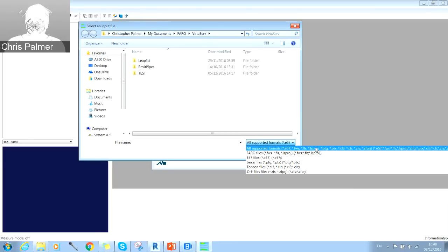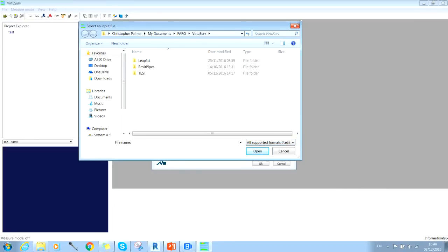And that does need to have the same coordinates as your RCS files or your RCP project in order to make the link work correctly. So really don't update your origin in Recap if you're going to be using this link. Is this the answer? Okay, thanks, Chris.